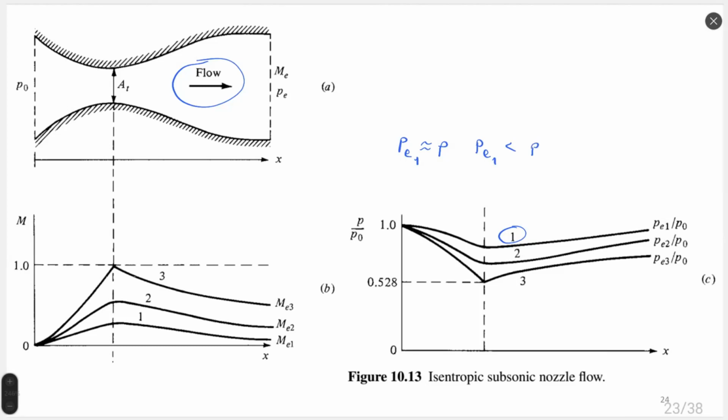Not so much. So what if we have a small pressure gradient? It means we have small energy for acceleration. Energy and acceleration are proportional to the pressure gradient according to our flow equations, if you remember. So if we have small potential to accelerate, acceleration will be very small. It's also shown on the graph of Mach number, picture B, case 1.